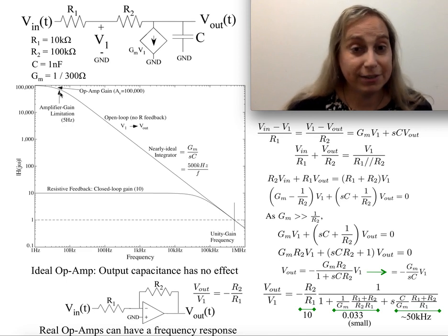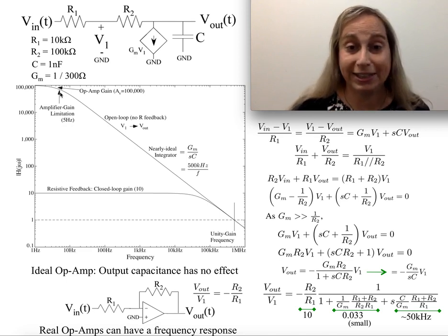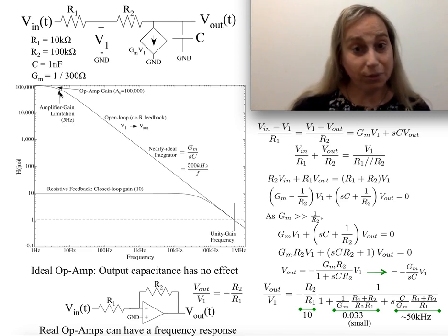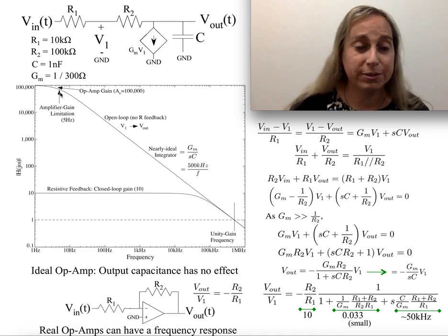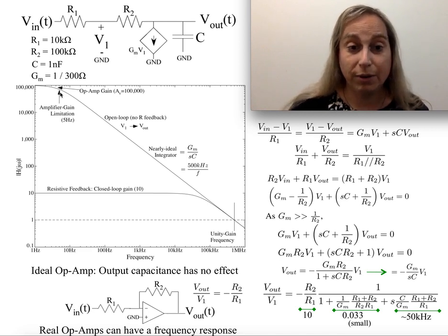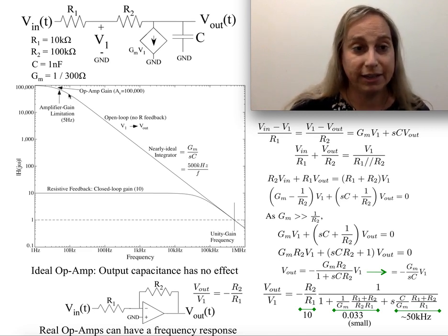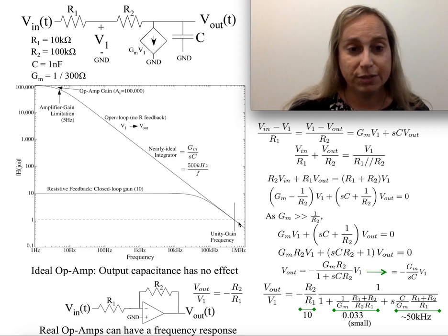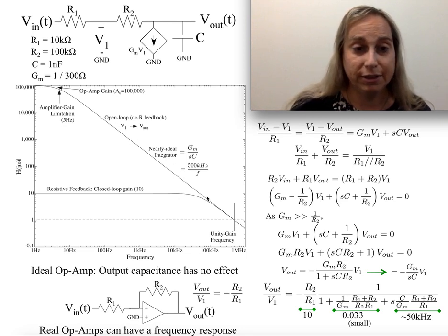This is always a surprising thing, and the first time it became clear to me that op-amps actually look like this, I thought, wait, but the ideal model is only sort of true. But it turns out even with the frequency dependence, it still works out well. Maybe a better way to look at it is that I've got this region over 5 or 6 orders of magnitude typically, where the gain just drops linearly with frequency.